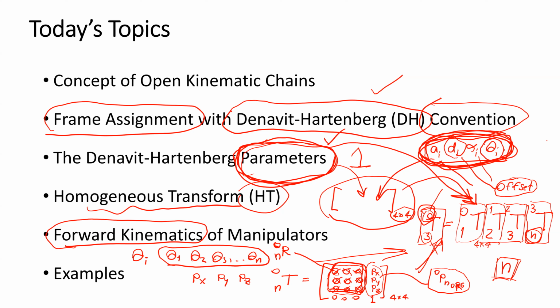For the joint angle, if the joint is the revolute joint, the joint angle can be controlled by rotational actuator. So maybe for the input of the system in the joint variable, it can be the theta for revolute joint, or it can be the d for the prismatic joint, and we can obtain the position.